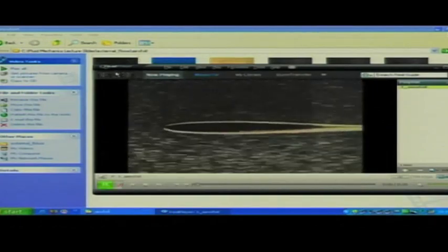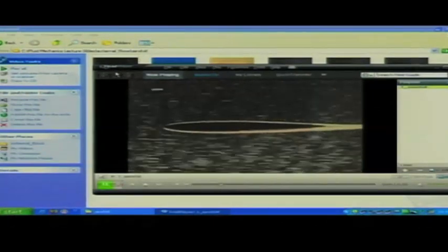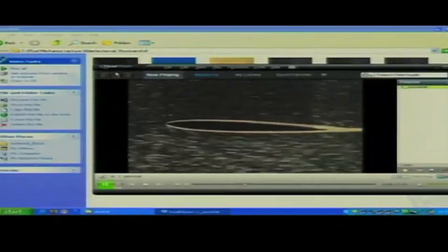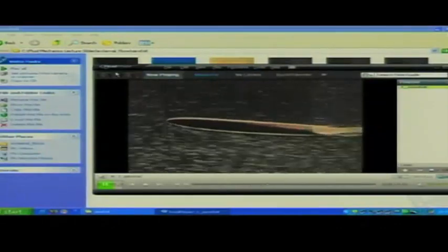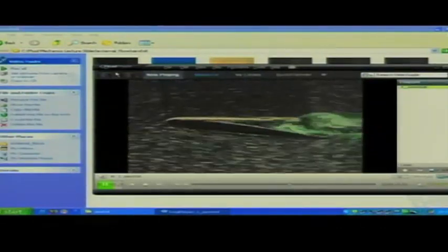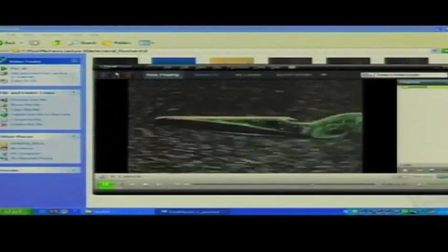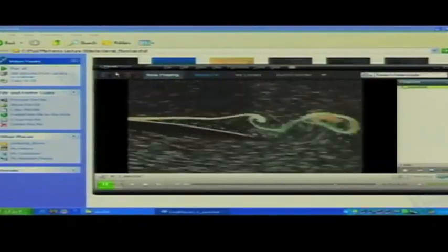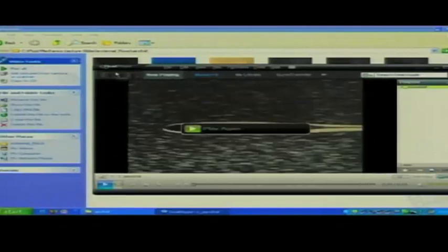So why is the lift force small when alpha is high? If you calculate the lift force, obviously that will come from the proper evaluation of the expression. If you evaluate the proper lift force for flow past an aerofoil, you will see that it will increase with alpha so long as you do not have a large separated region.